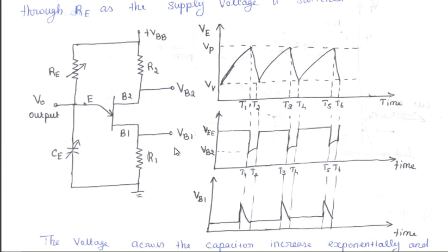After the peak point voltage of the UJT is reached, it provides negative resistance to the discharging path, which is useful for the working of the relaxation oscillator. As the capacitor voltage reaches 0, the device cuts off and capacitor CE starts charging again. This cycle is repeated continuously, generating a sawtooth waveform across CE.